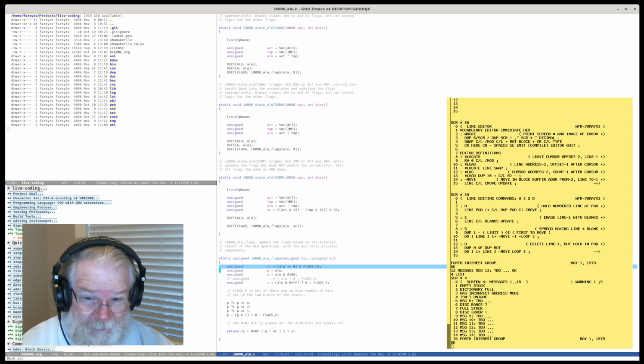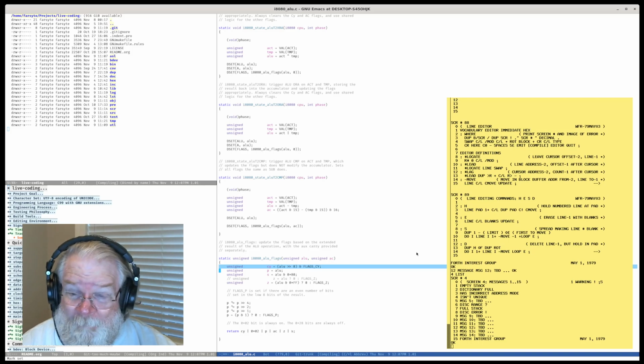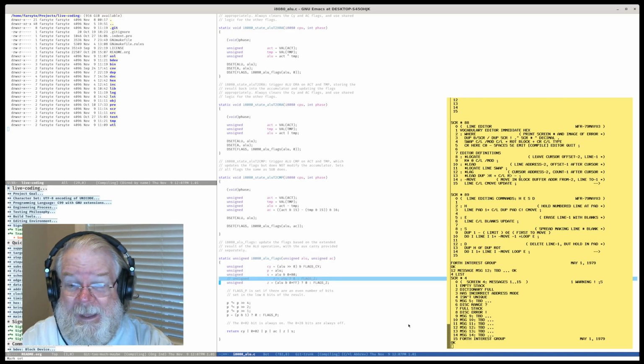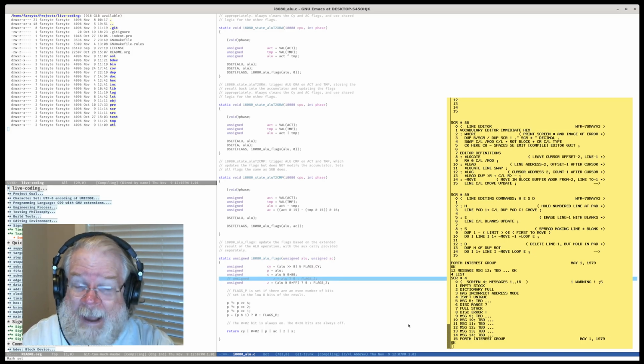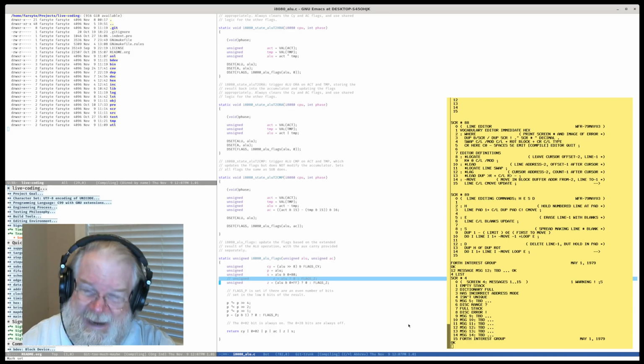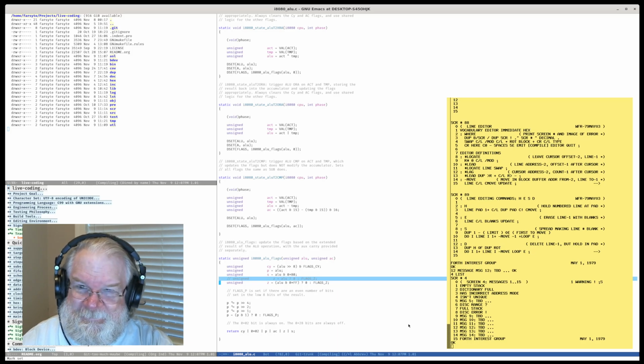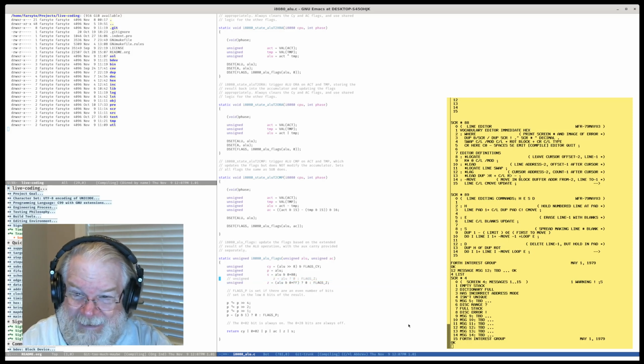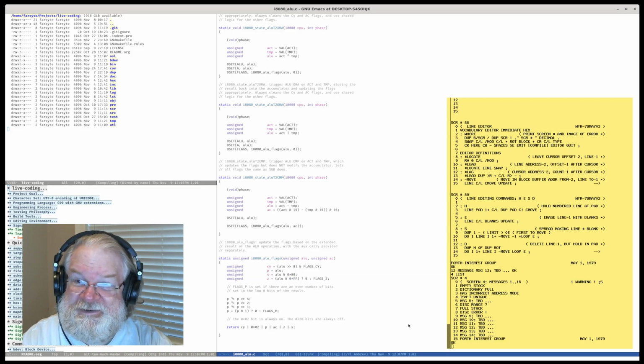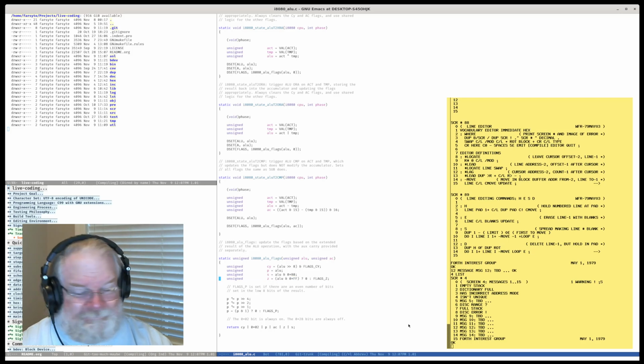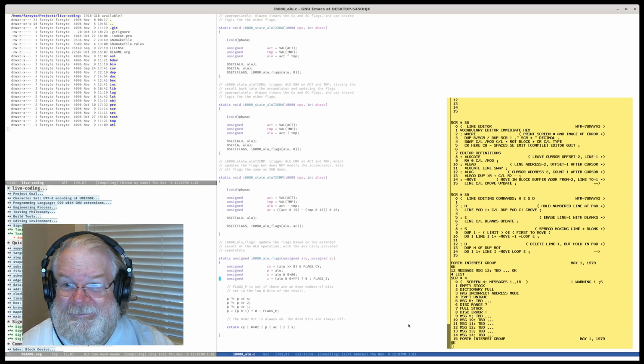Adding A to itself should turn on the carry, and it should turn on 0, and it wasn't because of that line. That took me a lot of hours because I thought I had a bug in Forth, and it came down to a JNZ which was executing when it shouldn't. It took a while before I realized that it was that add instruction that wasn't setting the Z flag because the result was 256. Dope. Anyway, that was the only actual debugging I got done here.